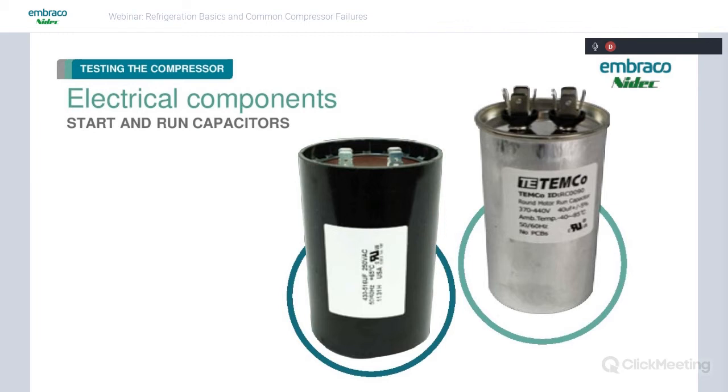And these are designed to be in the circuit at all times to increase running efficiency. So the way they're designed, they can be energized all the time. And basically, as we stated before, the start winding gives us extra starting torque, and the start capacitor and the run capacitor gives us additional running torque and efficiency.